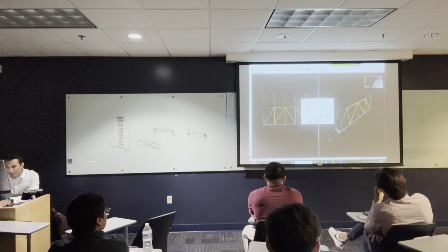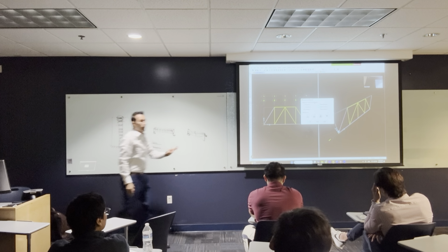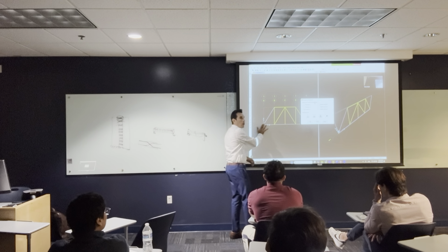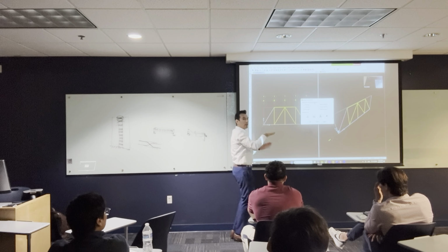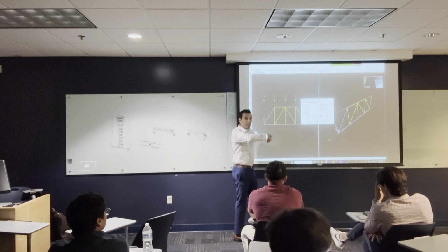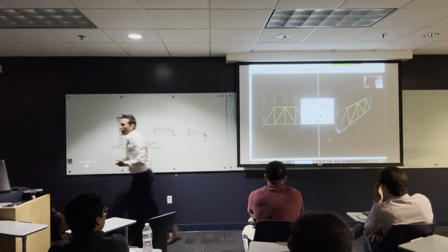Look what is happening if I pick the roller. It says restraint from joint to local direction only in 3. So basically this joint is gonna only have a restriction to move up, but it can roll in the X and it can roll in the Y. It can rotate about X, about Y, about Z. Okay, that's the only thing that we have.